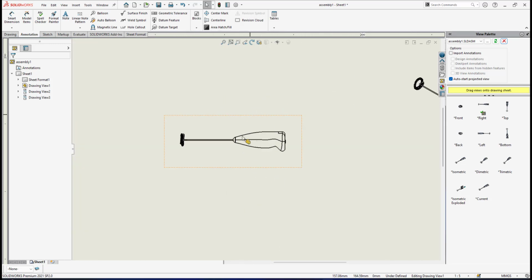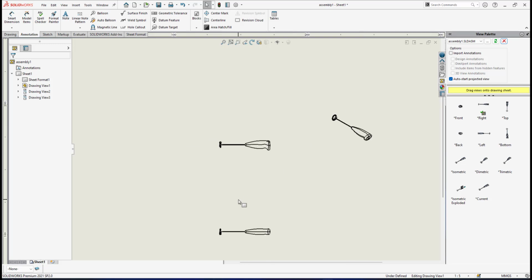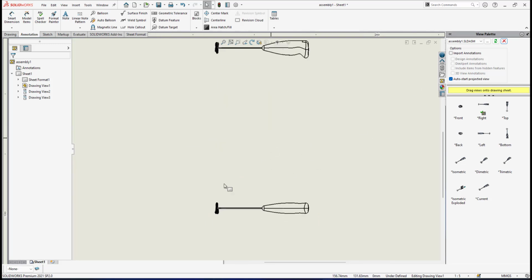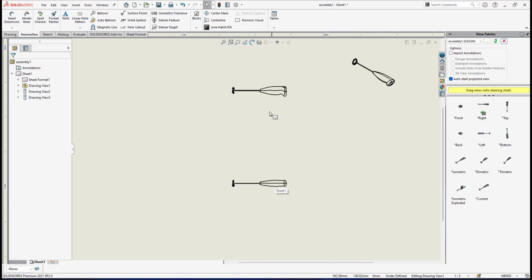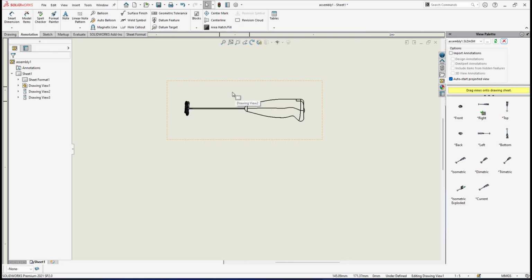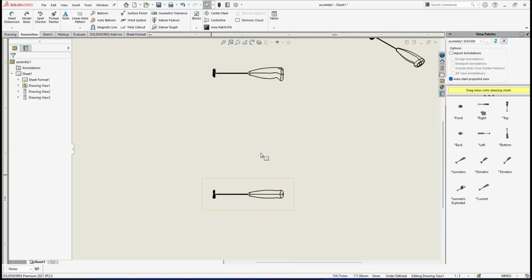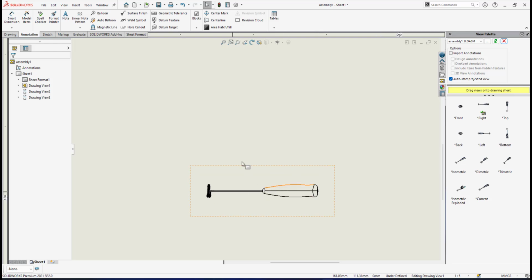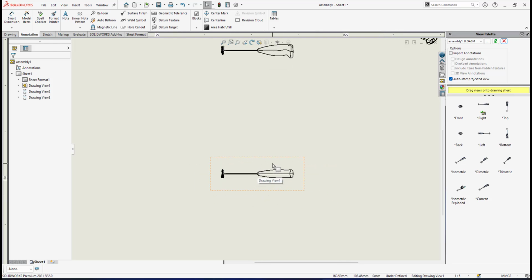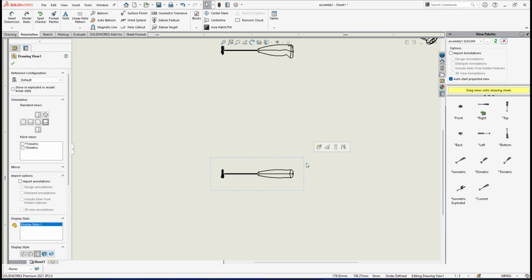So it means that for this top view, I will do a full sectioning, and my front view will be the view that has a section view with a section line. So it means that my top view, my top projection, my plan view, has a full cutting plane, full sectioning, and my front view at the bottom is not like this, it will be in section view. So what I mean here, I will delete it.